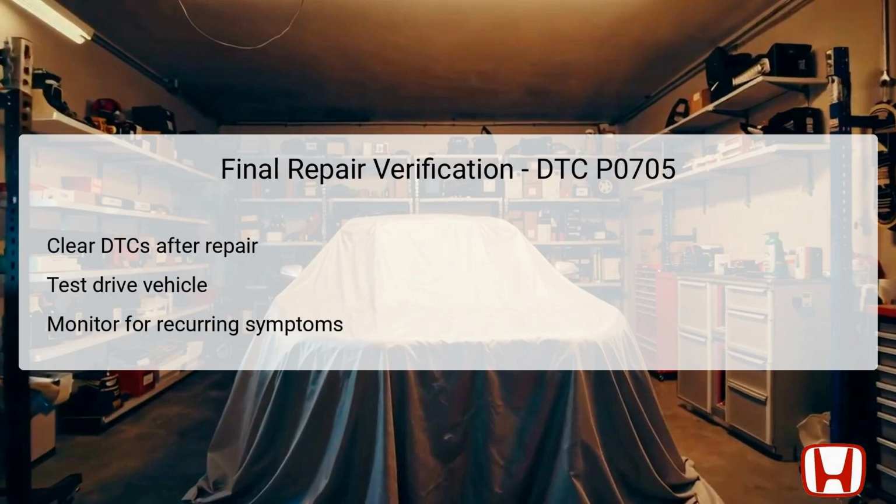Once repairs are completed, it is imperative to clear any DTCs stored in the PCM to reset the system. This will ensure that the vehicle starts with a clean diagnostic slate. Following this, conducting a test drive is critical to put the component back into a real-world operation scenario and assess whether the problem has been effectively resolved.